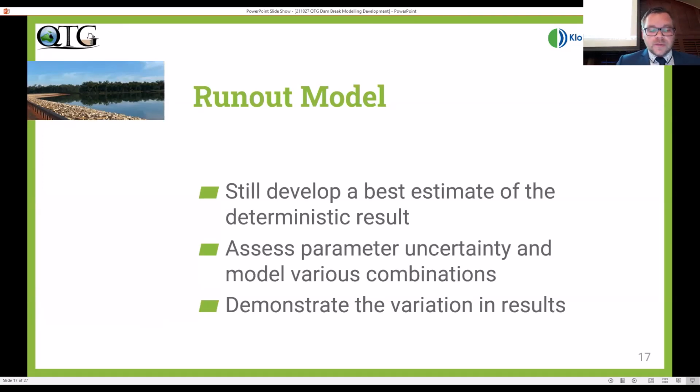Where I see us moving in the next year or so is, well, sensitivity testing across different projects have shown that we can have great, precise downstream models, but the potential variation associated with parameters that we put back up in the facility have a far greater variation and impact on what's happening downstream than the actual 2D model calculation. So obviously getting those parameters up the front right removes that problem, but we know that that's not always easy to do. What we can do, however, is approach the greatest areas of uncertainty with a probabilistic assessment.